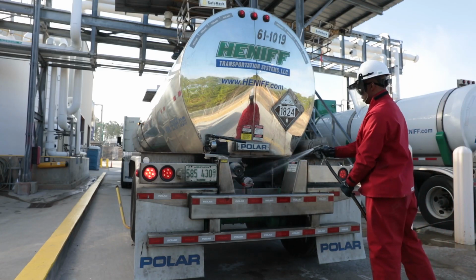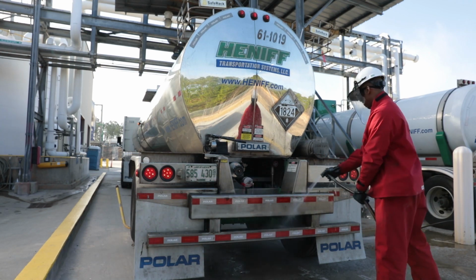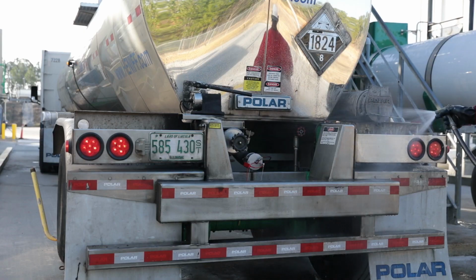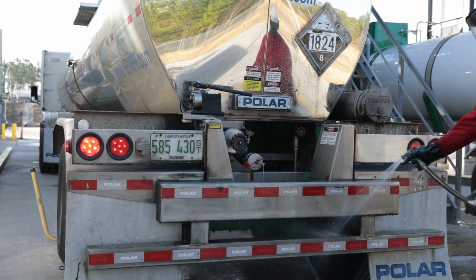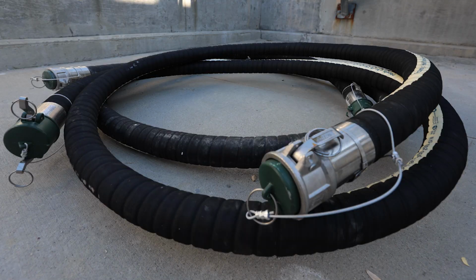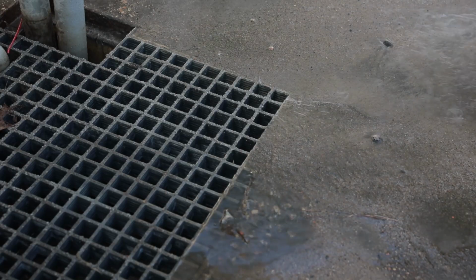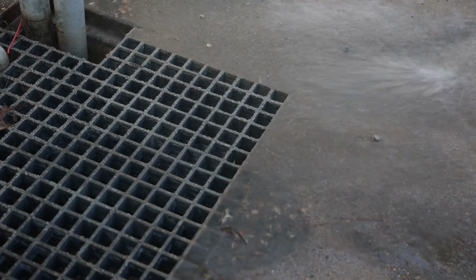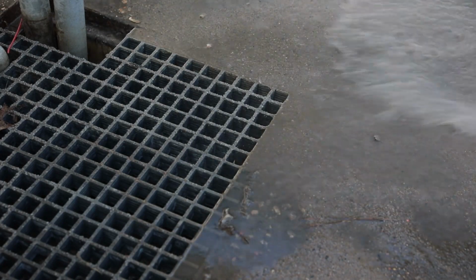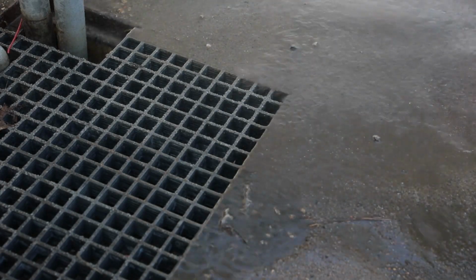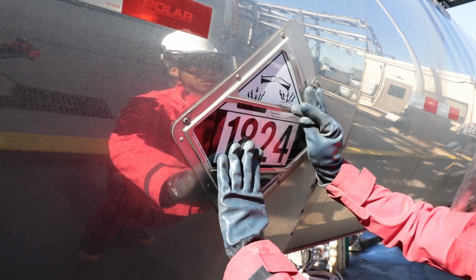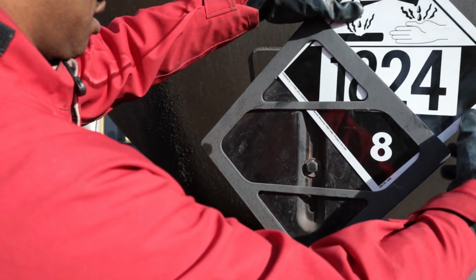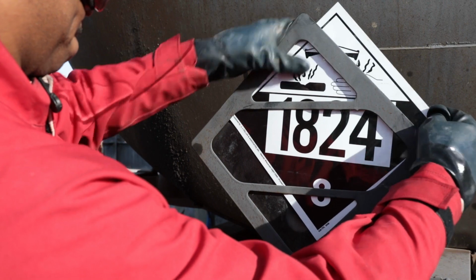At the completion of any unloading process, wash any caustic spillage from the tank cars or tank trucks and other equipment to protect personnel who may handle the car and to prevent corrosion. Wash out the hoses and process connections if subject to leaking. Wash water should be collected through a suitable collection system and disposed of in a manner that complies with state and federal regulations. Replace any damaged, faded, or missing placards from the tank car or tank truck prior to releasing for transport under DOT regulations.